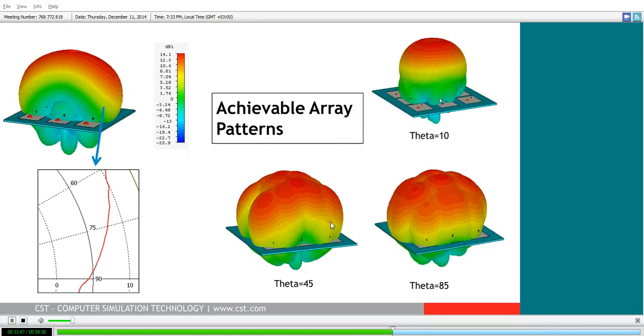And you can see that obviously for the smaller scan angles, this is pretty okay. As you get up to theta equals 45 degrees, though, we start to see some interesting trends in the steered array. In particular, we get some nulls here on the sides, the horizontal sides of the array where we have some blindness. This is something that we could look at tackling potentially by adding a token amount of diversity to our antenna design, perhaps by rotating a secondary array within the device. It's also worth noting when we're looking at these swept patterns that clearly this is a hemispherical array. These square patch antennas operate off of a ground plane.